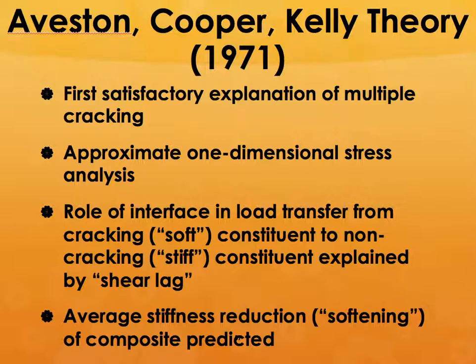They were the first ones to satisfactorily explain the phenomenon of multiple cracking. They did what is called one-dimensional stress analysis, and they figured out the role of the interface in load transfer from a soft constituent to a hard constituent. This process is called shear lag.